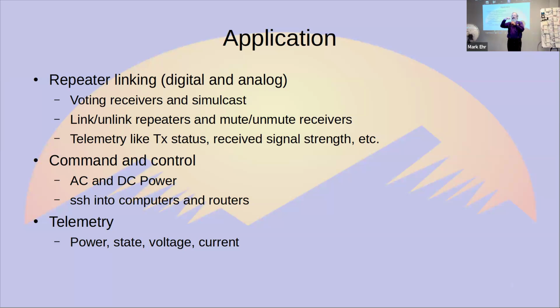And obviously, as you can tell from the polarization here, these are actually dual polarization radios. So they have 2 channels that are at 90 degrees to each other, and the antenna also supports that cross polarization, so that you actually have the 2 channels, and the radio is smart enough to know that it talks on this channel versus that channel. With the other radio, it automatically syncs that up.